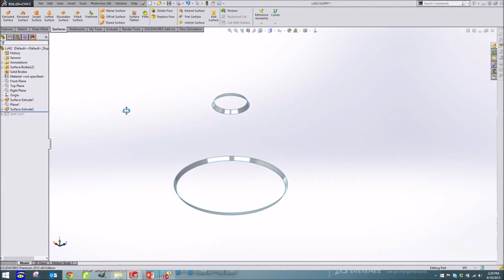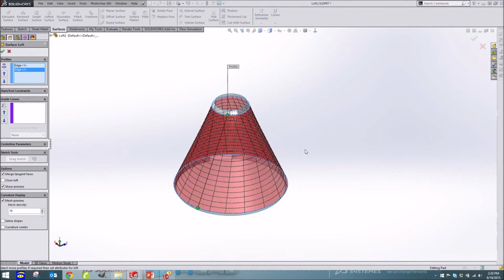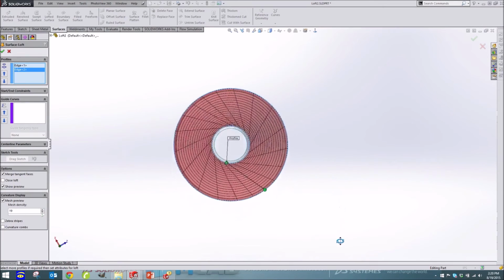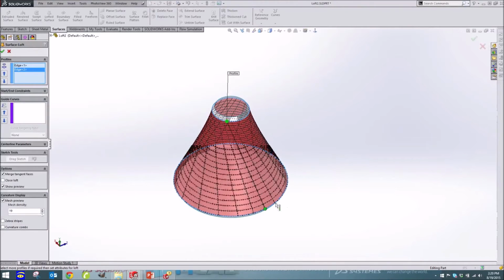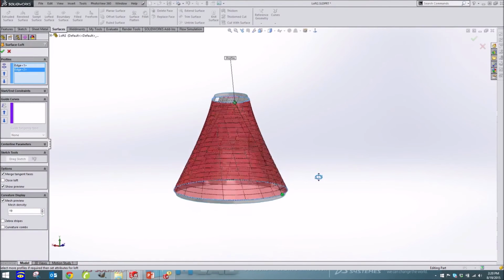Another difference with the loft is we don't have a whole lot of controls at the ends of the lofted shape. We do have the ability to control the direction, but like I showed earlier with the boundary curve, where I can control the endpoints at each profile, with a loft, I can only control the direction.